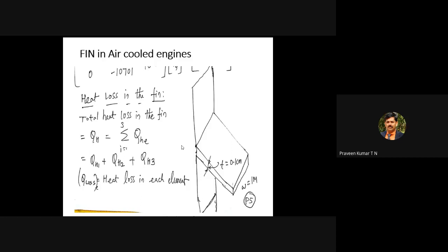Otherwise, if the temperature of the engine increases, because the piston is made of lightweight material, the piston may expand. When the piston expands, it may get stuck inside the cylinder. Some amount of heat is used to do work. During the combustion process, heat is generated due to burning of the air-fuel mixture. Then some amount of heat is converted into mechanical work by pushing the piston in the forward direction, and it will generate the power. Finally, it can drive the vehicle.